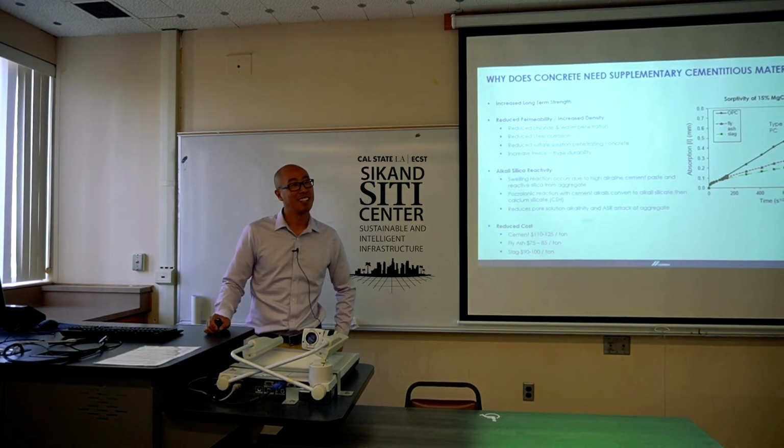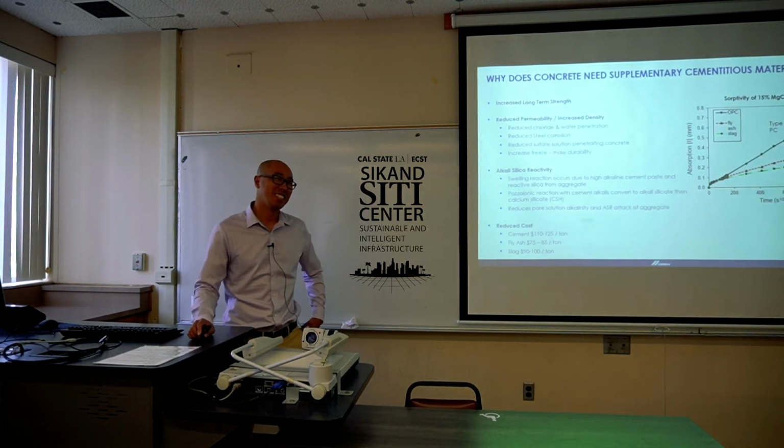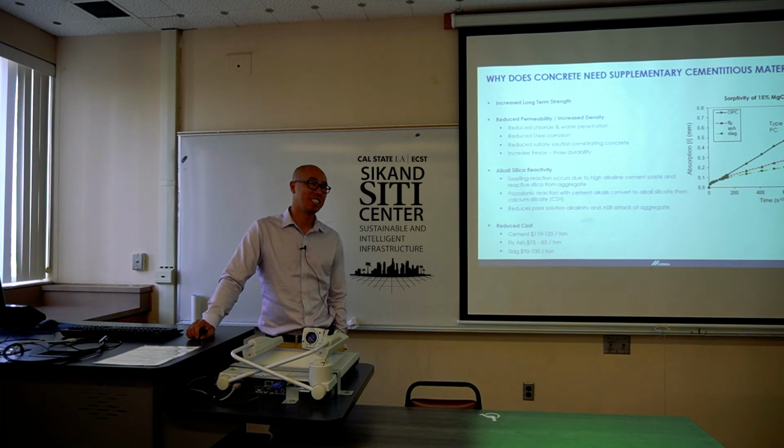I have a bunch of questions. Sure. Is there a possibility of using 100% fly ash or slag and completely replacing the Portland cement? It's possible because there's a similar reaction, but we haven't done any lab testing using only slag. But I think there's some possibility.